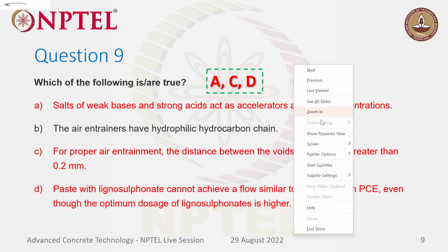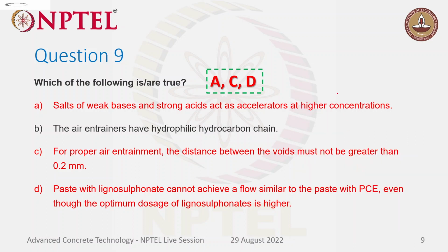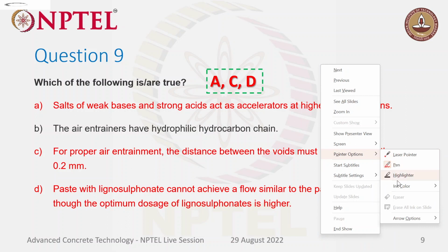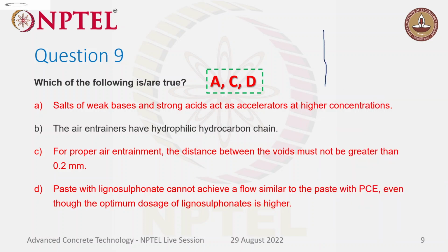I don't know whether I will be able to draw it now. Let me try to draw it for you. Just a minute. Yeah, dark blue. See, if it's a water reducer, there will be a long polymer backbone chain, and then there will be side chains, right? The side chains will have a negative sign, so the whole chain will have some charge, right? What happens is it will surround the cement particle and impart a negative charge. It separates from water, and it gives more water so that the cement paste will be more workable. There will be free water.